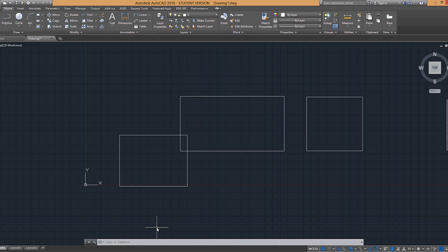Note with this option, as we go further, we'll see why AutoCAD commands and entries do not contain spaces, and that's because that space means an enter. So if you have a compound command, one that contains multiple words, a lot of times it'll treat it as one word, or you might even see an underscore, because the space bar is actually enter. That gets a little bit tricky sometimes. And then the other way is by right-clicking on the mouse.